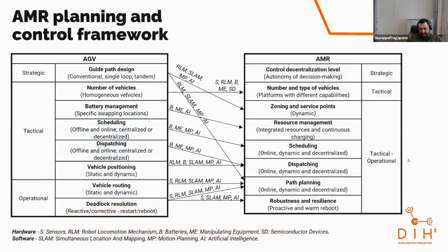Path planning also gets a little bit more interesting because with AGVs, for example, the vehicle routing was especially focused on not having a deadlock, so that it's not moving against another AGV, because if they're on one path, they cannot drive around. In path planning with AMRs, you have a totally new opportunity to think, because an obstacle like a pallet in front of it doesn't need to be a stop.